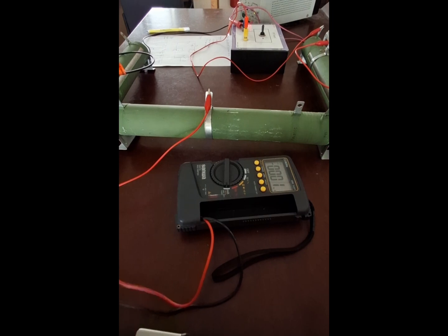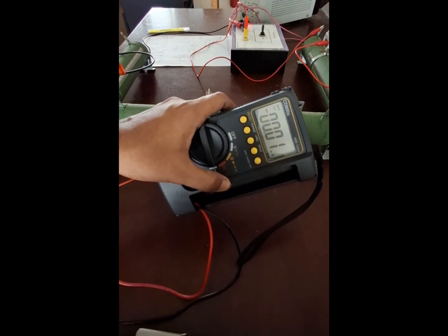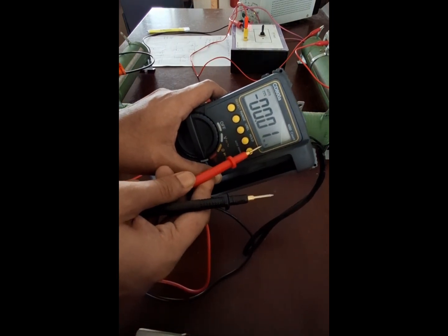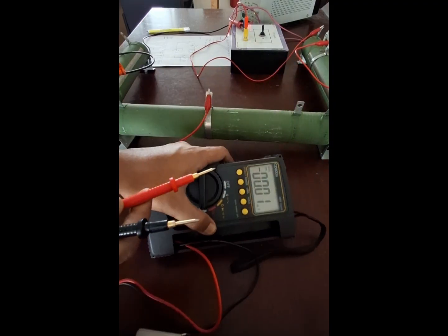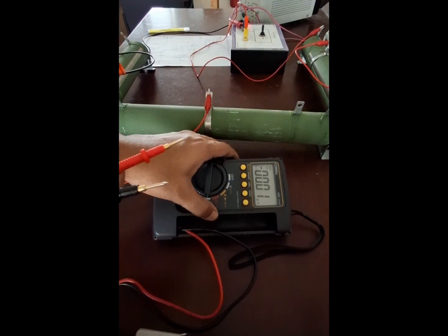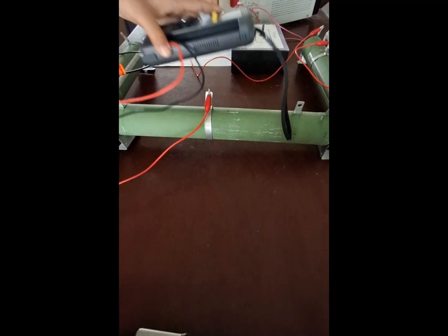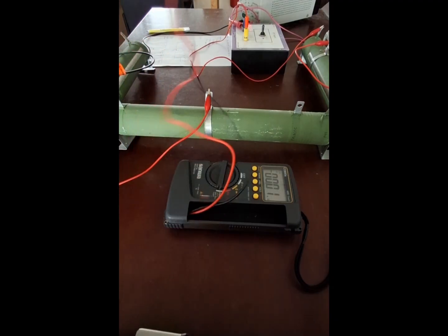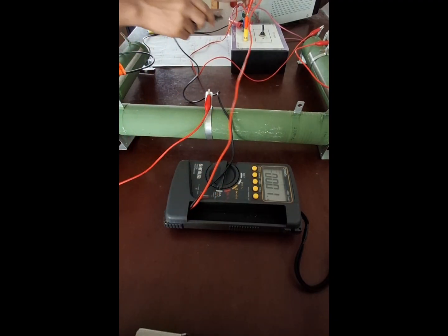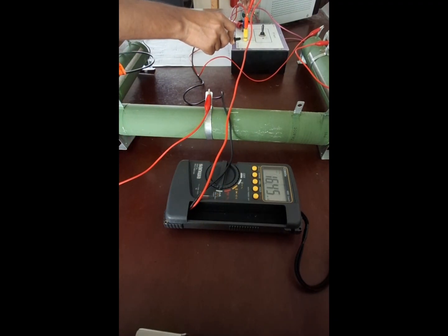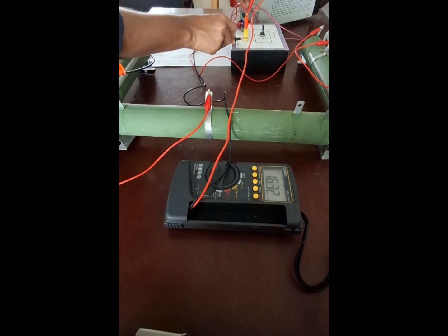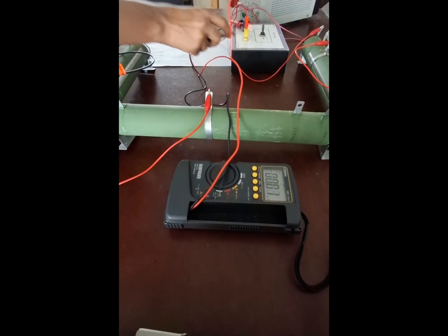So we will see that our multimeter is now in milliamps, that is here we see the parameter is in milliamps. Now we will measure the current through the SPST switch. So for that we have turned off our SPST switch, so we can see that it is turned off. Now we will measure the current, so we can do it. Now we see our multimeter is showing some value, that is 16.47 milliamps, we can say 16.47 milliamps.